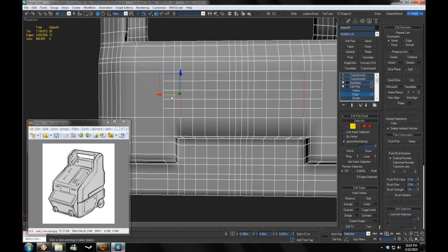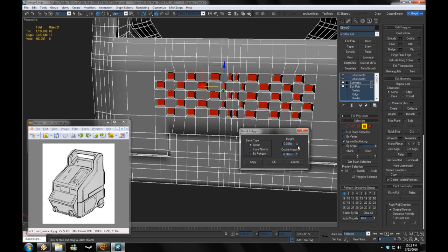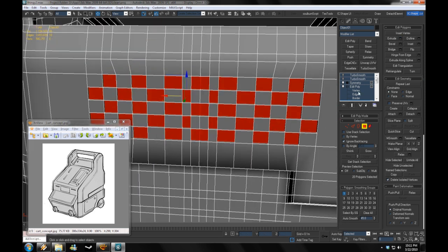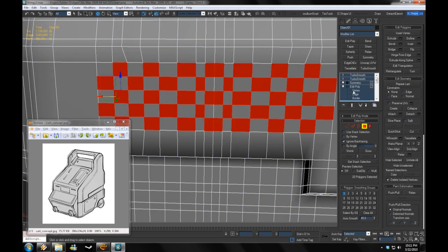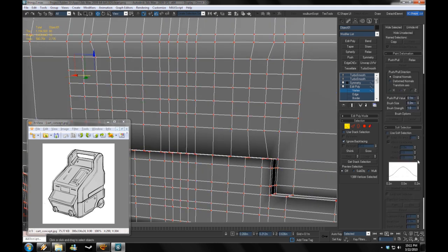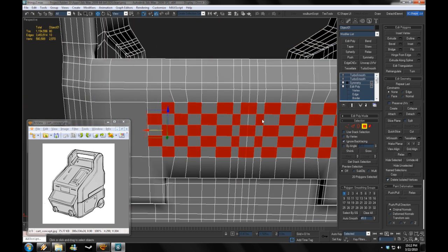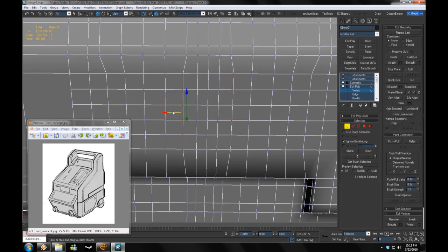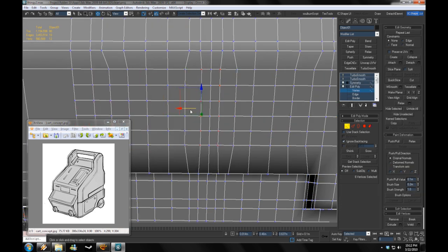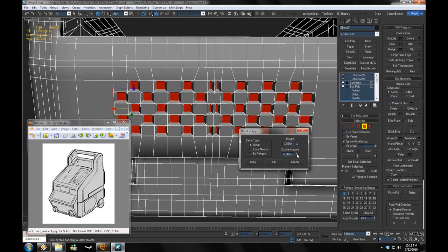And as you see, I made my mesh quite dense, and I'm just making it more even, as you'll see here. So have a look at this. Pretty decent. I'm going to have to do it by group. Get everything scaled down as need be. And also, for whatever reason, Max decided to make duplicate vertices, which is an unfortunate bug. I don't know why that happens, but we can get around that by just welding everything by a very, very, very tiny radius.